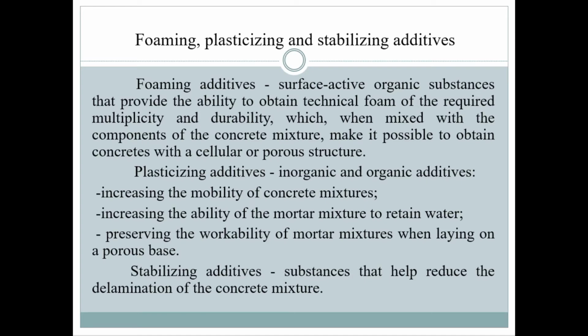Foaming, plasticizing, and stabilizing additives. Foaming additives are surface active organic substances that provide the ability to obtain technical foam of the required multiplicity and durability, which, when mixed with the components of the concrete mixture, make it possible to obtain concretes with cellular or porous structures.